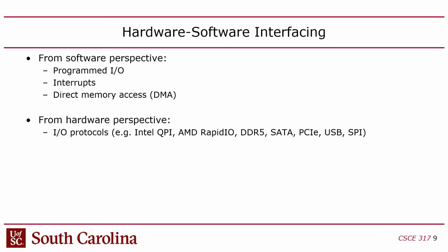who's writing a Linux driver, the way that you talk to hardware is through three mechanisms. There's programmed I/O, which is where you basically just use load and store instructions at special I/O address ranges. When I say I/O address ranges, I mean the effective address of the load or store would fall in between these special magic ranges that correspond not to memory but to hardware devices. And then you use that to read status registers and write control registers, which are basically just words that you pull out or send to the peripheral that have different meanings and different functions depending on what the user guide says for that specific peripheral. And generally speaking, those registers are divided into fields, and you're usually bit twiddling within those fields.